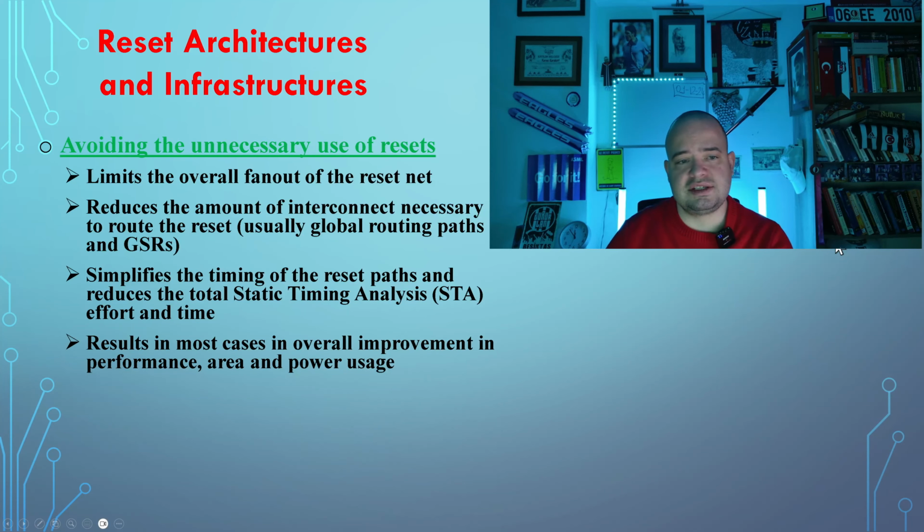So in summary, avoiding the unnecessary use of resets limits the overall fan-out of the reset net, reduces the amount of interconnect necessary to route the reset, usually global routing paths and global set resets, simplifies the timing of reset paths, and reduces the total static timing analysis effort.